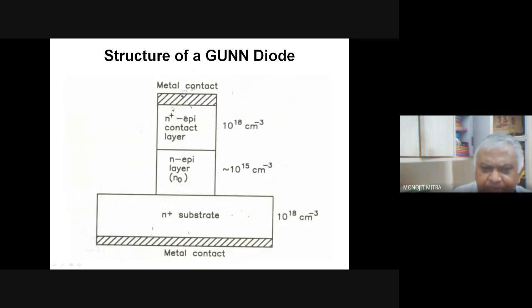And now again, across this semiconductor, there are two metal layers. I told you probably in my earlier classes that when there are two metal plates, metal sheets, metal rods or metal wires separated by some free space, free space meaning air or any other dielectric, rubber, plastic, ceramic, anything, then that gives rise to some capacitance. Because the metal plates are separated, charge carriers cannot move from one plate to the other directly.